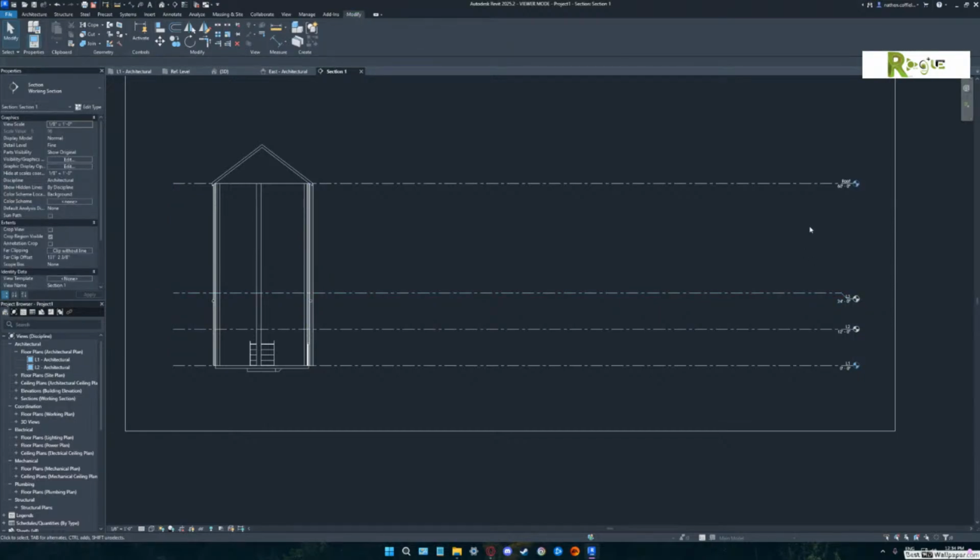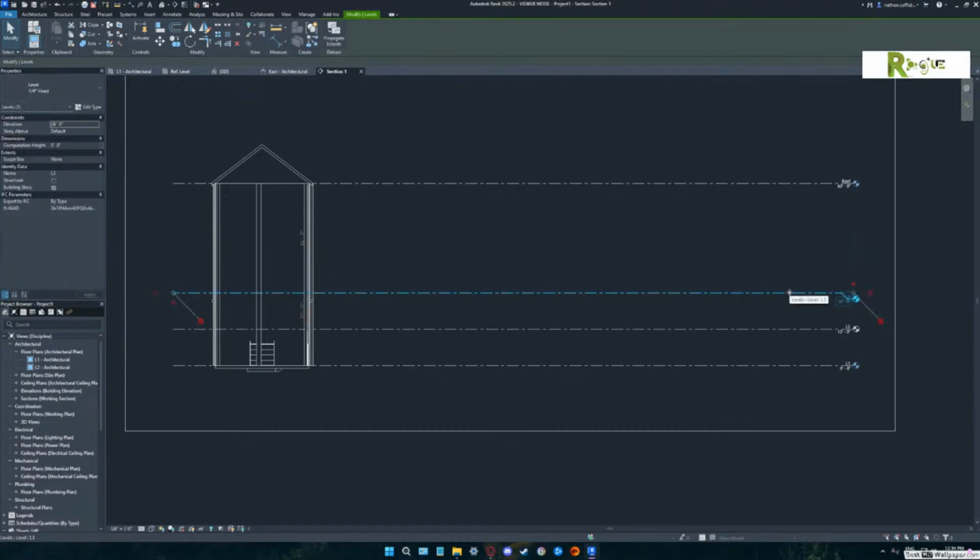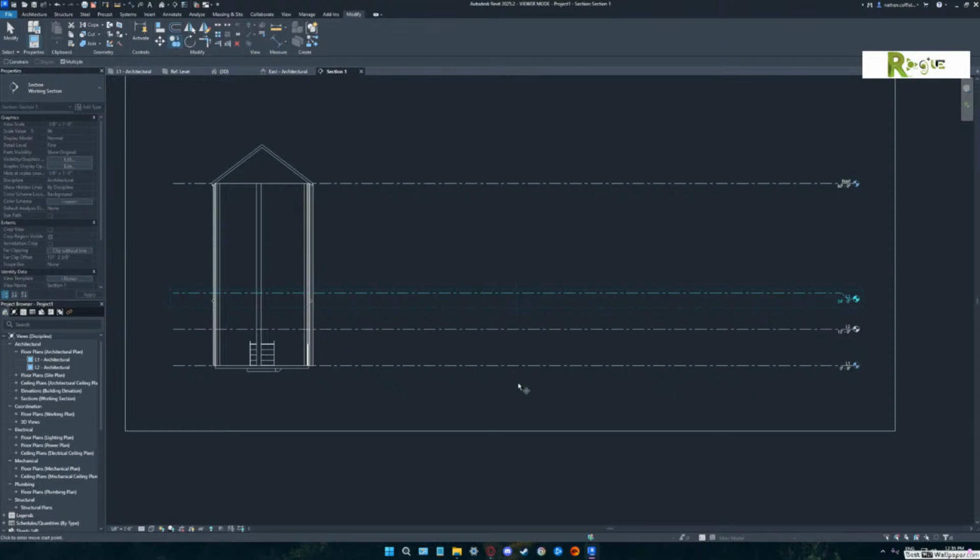All right. Now, what we did was we did the copy command. So if you pick L3 and copy it up 12 feet, remember how we did down? Yep. I didn't. Do I select or do I just start typing? Nope, you're perfect. You just start typing 1, 2.